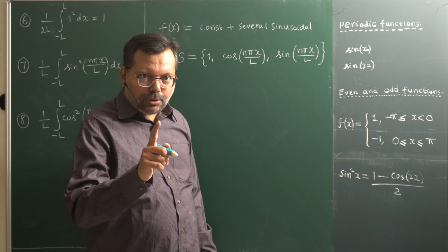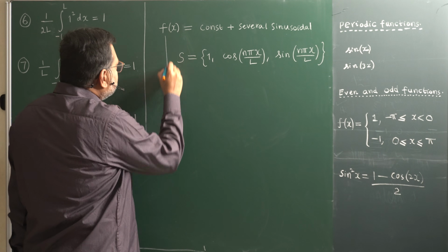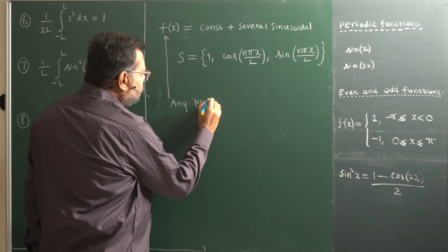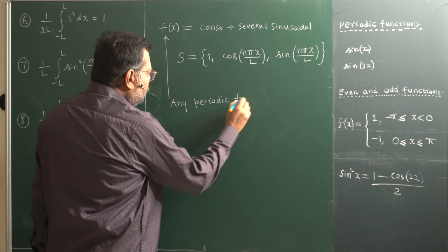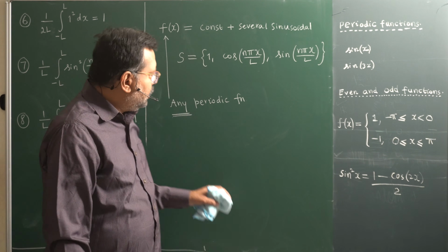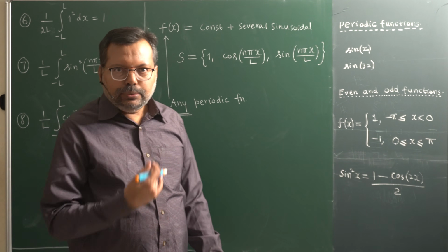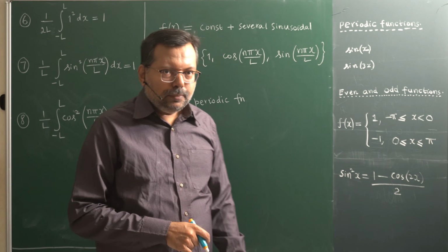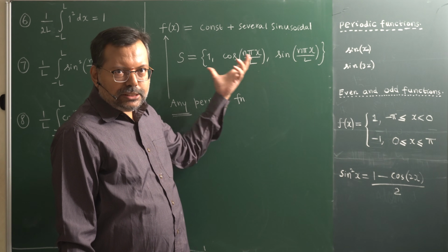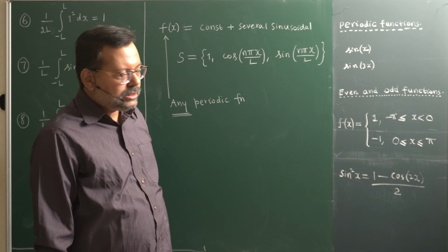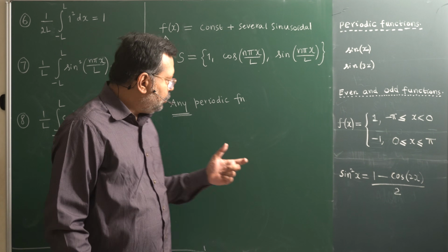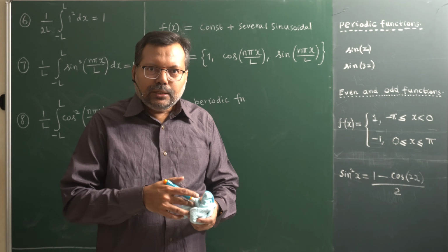You see how powerful this equation is, that this is not a particular signal. This is any periodic function. In mathematics we most probably use the word arbitrary. Arbitrary periodic function means you give me any signal which is periodic in nature, then we can decompose it only in terms of sinusoidals. The DC part is only shifting, so nothing will happen to the original structure, and the entire thing is decomposed into only sine and cos. Arbitrary means infinitely many combinations.